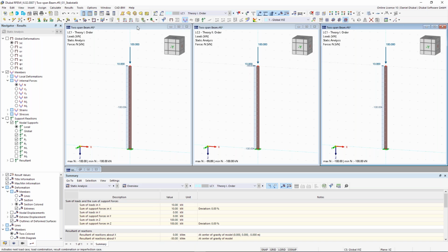So first of all, the normal forces, but for this fixed column, cantilever column, the bending moment is for me more interesting. Okay, so let's take a brief look. I think calculating the bending moment of this cantilever column is no big problem, because 10 kilonewton times 10 meters, so the height, this is my bending moment here at the support. This is according to the first order.